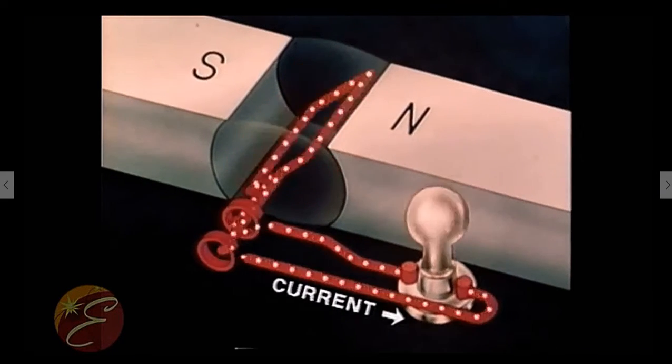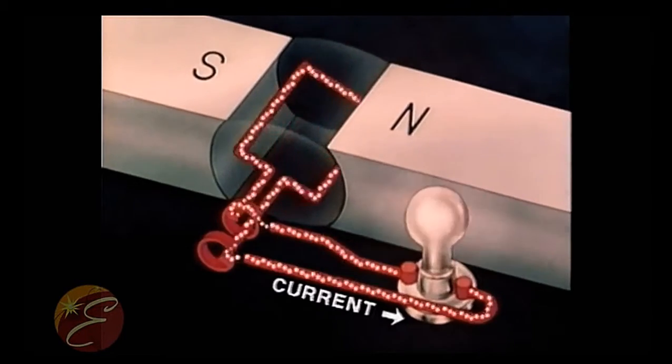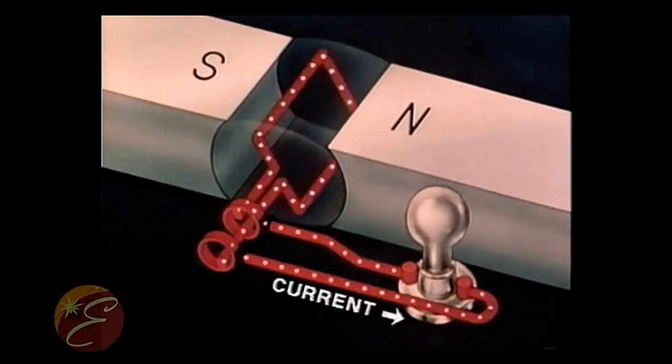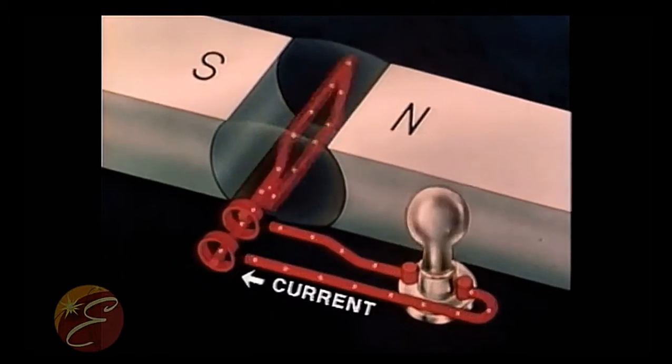Well, the electricity you get out of the wall is in the form of a sine wave. The voltage, or amount of energy each electron has, varies in accordance to a sine wave. To produce electricity like this, a generator is used. We know that a conductor moving in a magnetic field induces a current in the conductor, so if a loop of wire is rotated within this field, a current is generated.